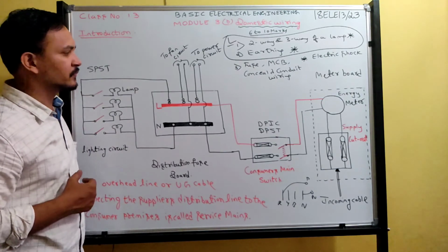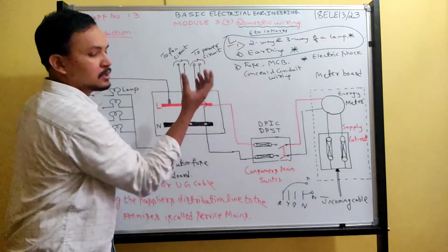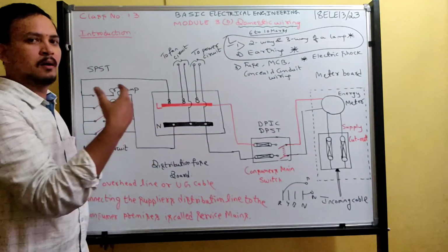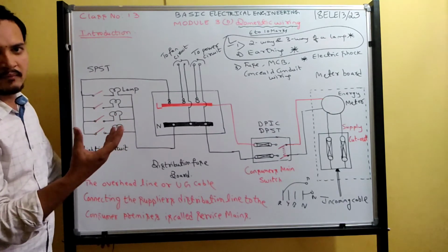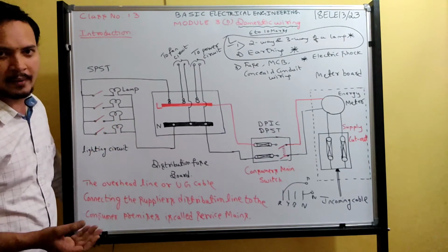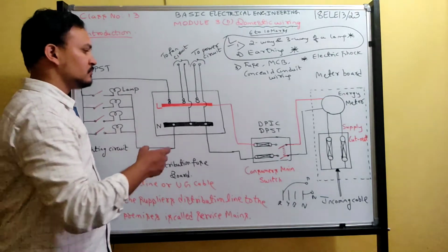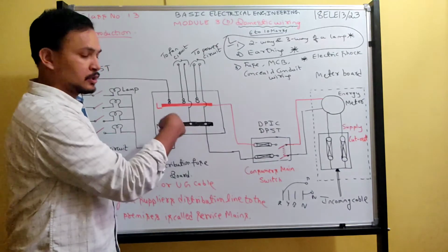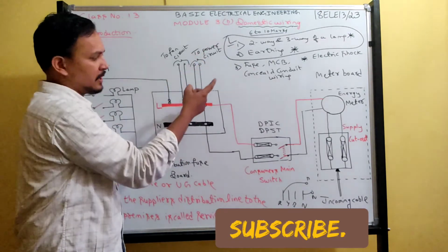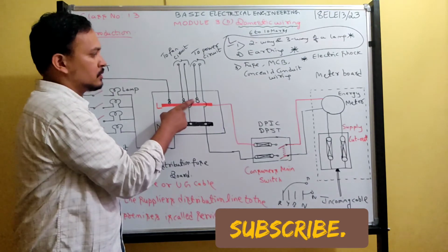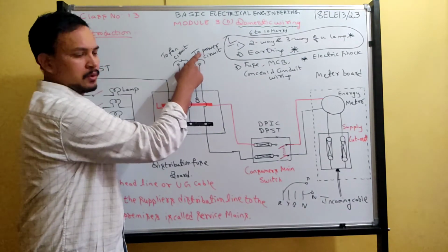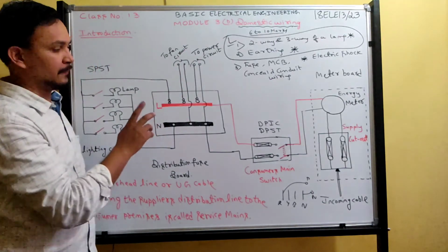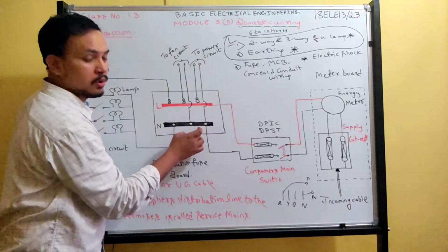Next, look here at another circuit, the power circuit to run a mixie. In the kitchen we have an electric stove and electric oven, which are higher power circuits. These can also take supply from this distribution board. Since the power circuit is separate, it is provided with a fuse. This fuse will go to the power circuit, operated by switches, and the switch should be connected to live only. The other end of the fuse will be connected to neutral.